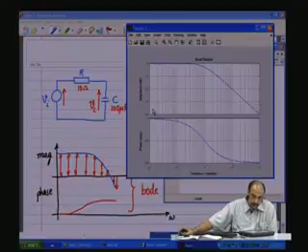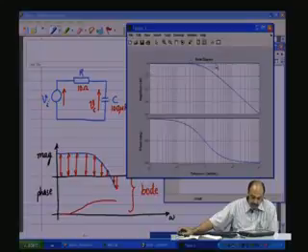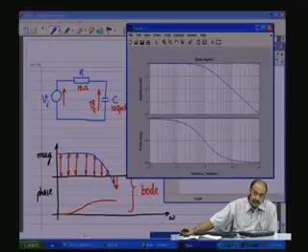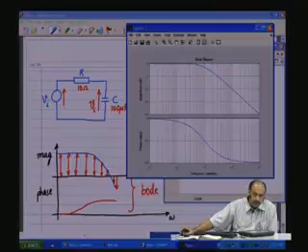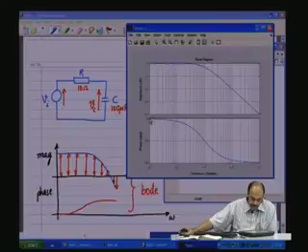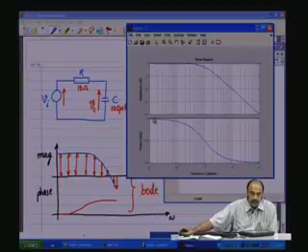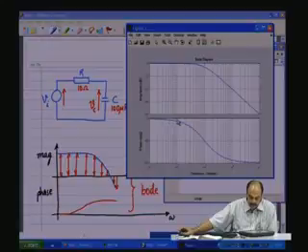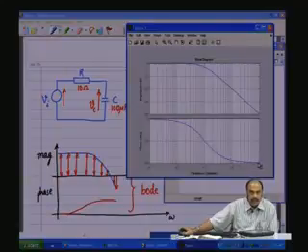So, that is how the meaning would be of this particular gain waveform. And look at the phase, that is, there is a phase shift between the input and the output. If you give a particular waveform of some particular angle, with respect to the input, the output is not phase shifted near DC frequencies, but the phase shift is gradually increasing in the negative direction because it is a capacitance, and ultimately goes to 90 degrees when the frequency becomes pretty high.